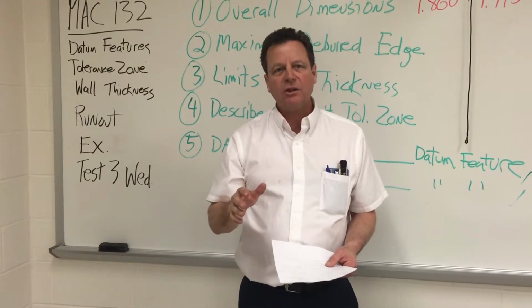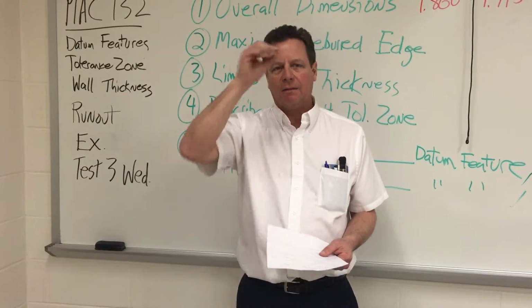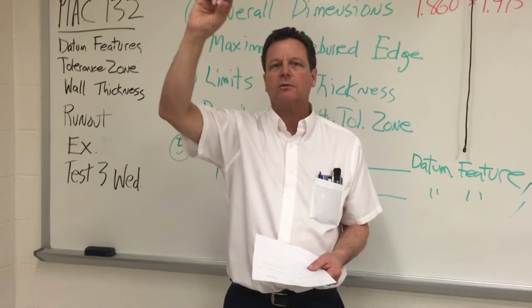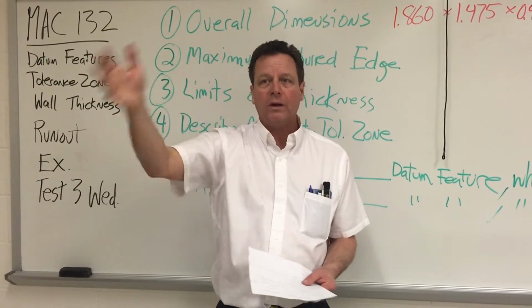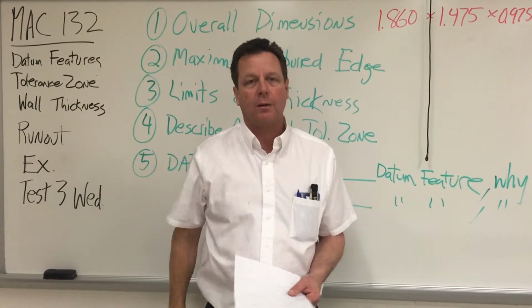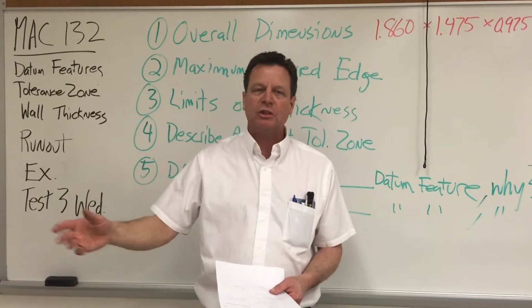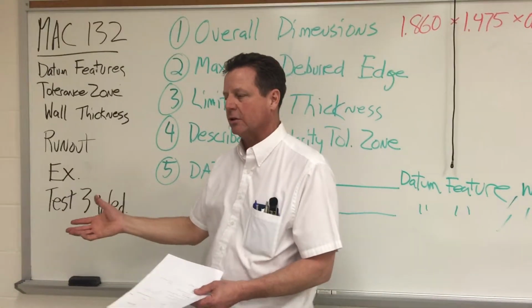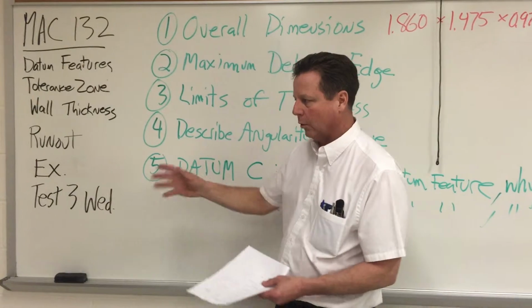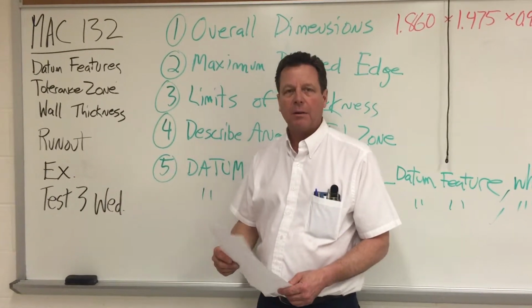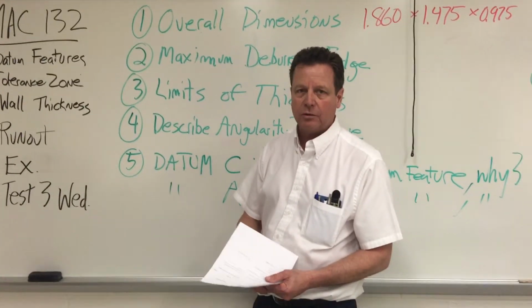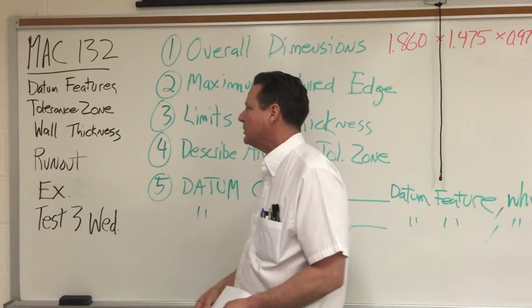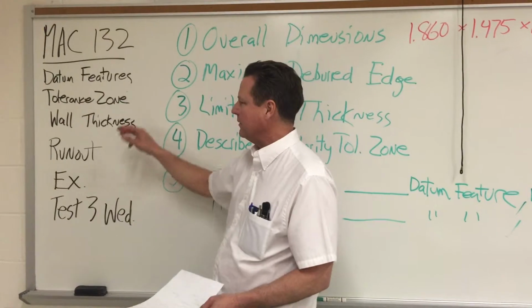You have to look at the GD&T for a long time and think about what it means in practical terms, not only for the shape of the tolerance zone, but what it's going to mean for how you machine it in the shop. Which machines are you going to pick? Do you have to have a surface grinder to do this, or will a milling machine do? Am I going to be able to repeat these parts enough, or am I going to have to use a CNC machine? So that is the shape of the tolerance zone.